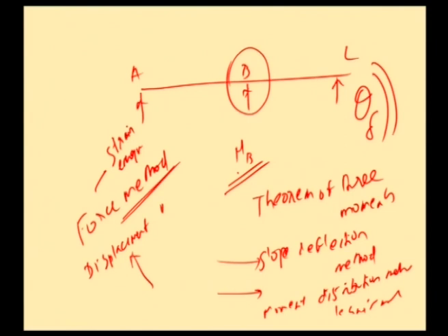That concept will be made use of in the slope deflection method and the moment distribution method or Kani's rotation contribution method. So, we have an idea of what is an indeterminate structure, how to find the degree of indeterminacy, and what are the methods available for solving indeterminate beams. We do not involve problems of this type. At this point we should be in a position to obtain the degree of redundancy of a structure, and explain what are the various methods available for analysis of indeterminate beams.